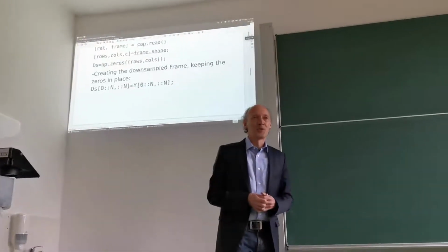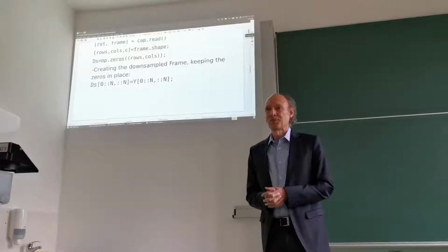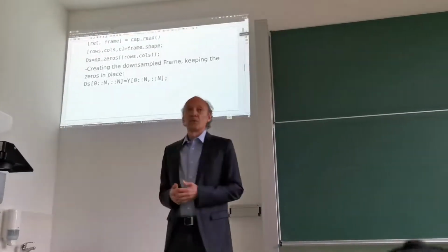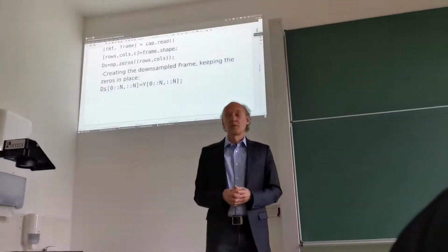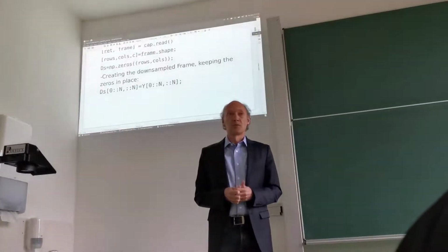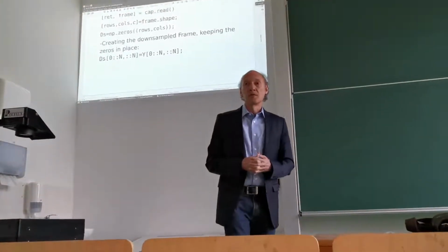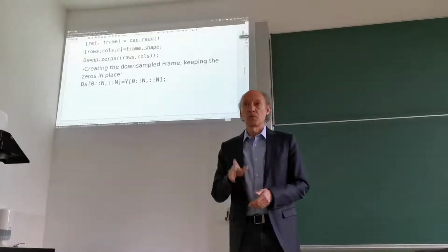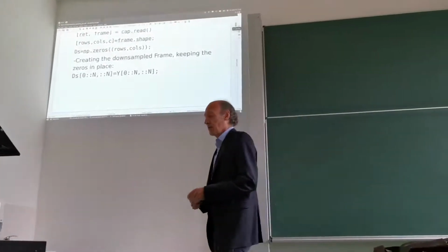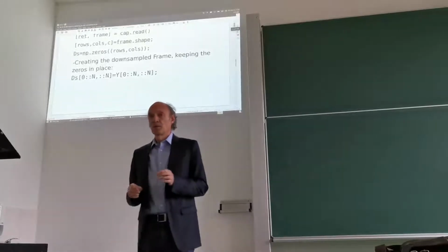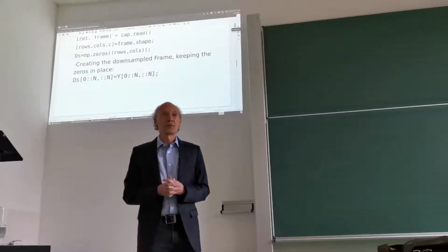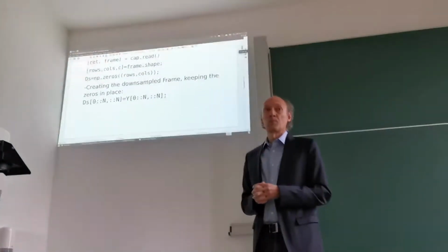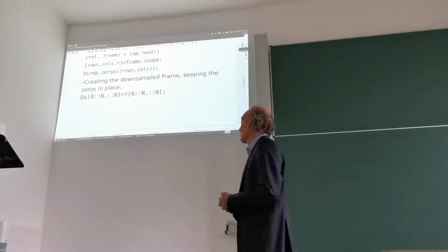Next session on Grundlagen der Videotechnik, Basics of Video Technology. So last time we started with sampling, downsampling an image. This is, for instance, what we have at the color channels. We have this color transform, Y to U V. Y is the luminance, and U and V are the chrominance, and U and V are downsampled. But downsampling can be problematic, as we saw last time.